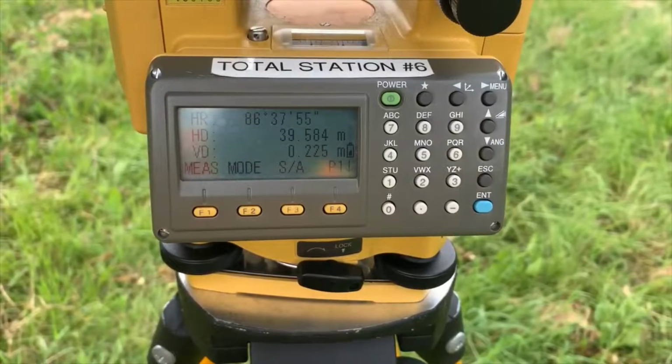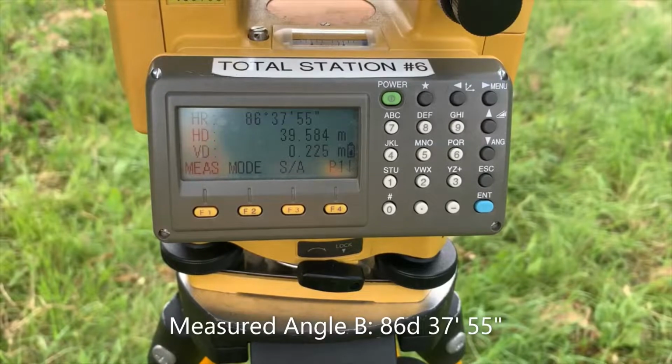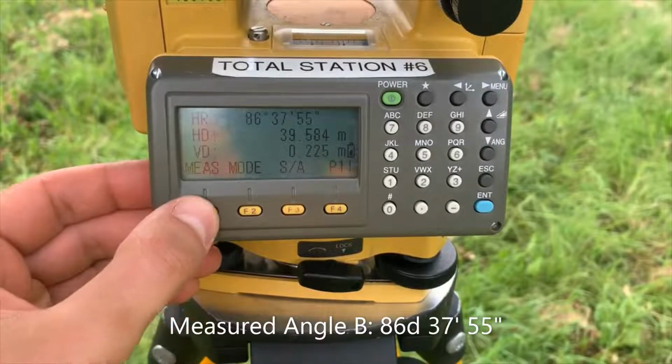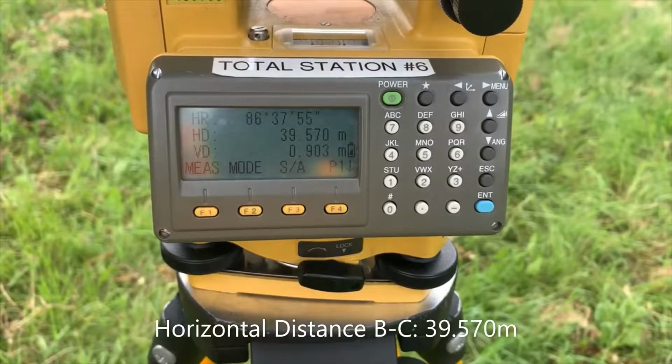So now I've sighted the total station at C6, a prism set up over C6. We can see our horizontal rotation is 86 degrees, 37 minutes, 55 seconds. We can push F1 to measure, take a measurement, and our horizontal distance from B6 to C6 is 39.570 meters.